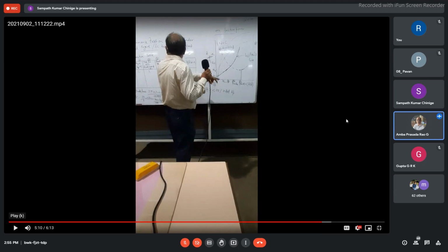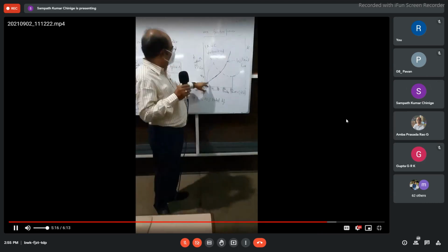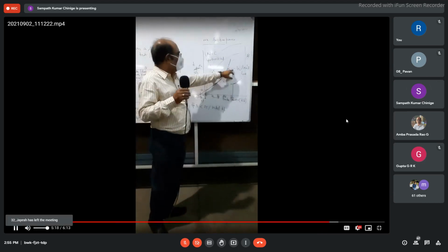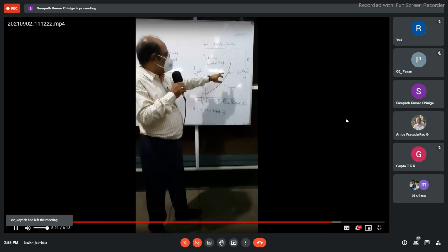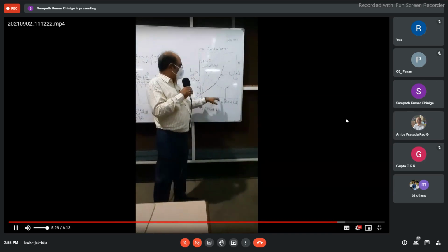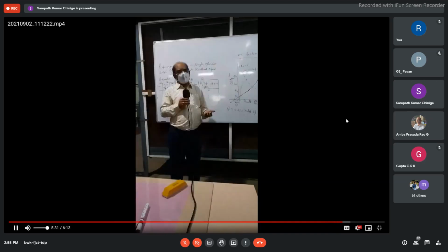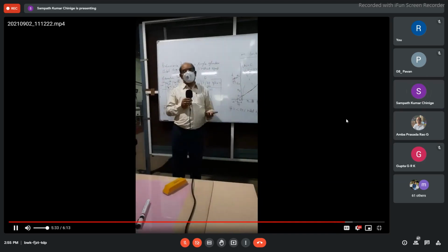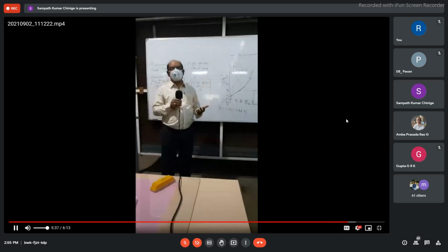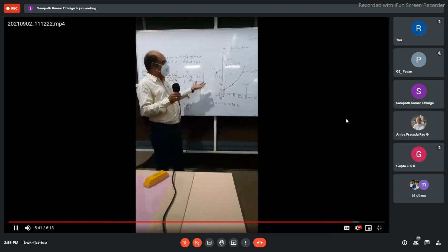So how this curve looks, I am trying to explain to you. For this graph, the x-axis gives the brake power values, and this line is what is popularly called the Willans line method. It is the fuel consumption versus brake power line. You need not go to a specialized method for getting the value of friction power of an engine. By conducting the performance test itself, it will give you the friction power, so we are indirectly getting the friction power of an engine.